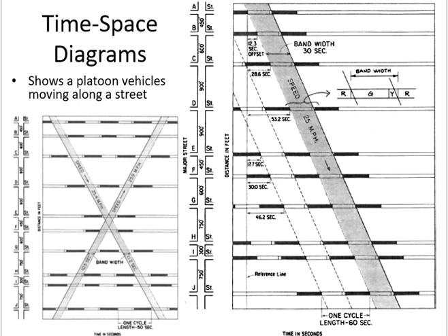Actually, they have shown it here. This is the last line. So this is the end of yellow, see? This was my intersection, right? So the first point is start of green. The last point is end of yellow. So I know the points to join. What about the slope? Do I know the slope of these lines? What is it? Speed, right? I knew the speed, that's why I could calculate the offset. So now I know the slope. The slope should be equal to the speed you have used for these calculations.